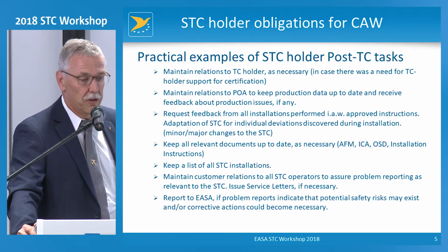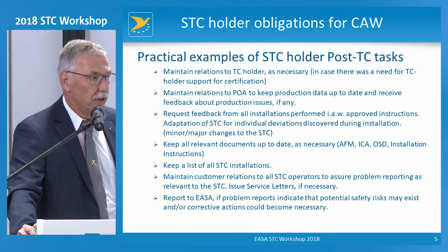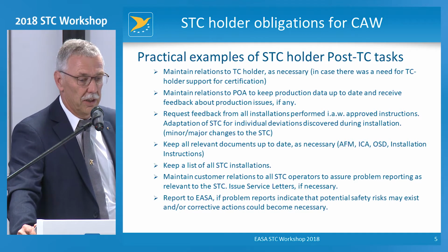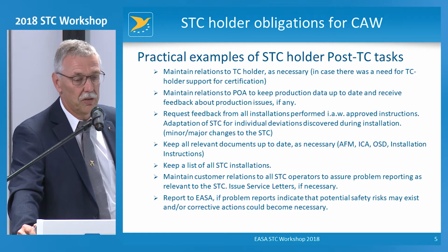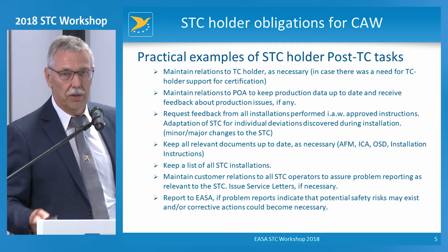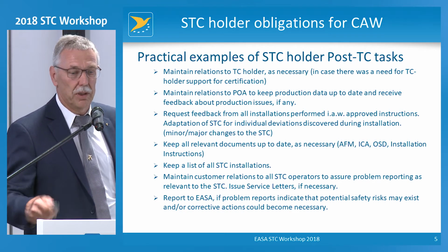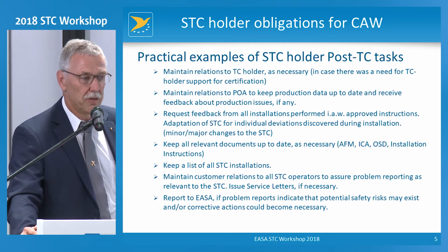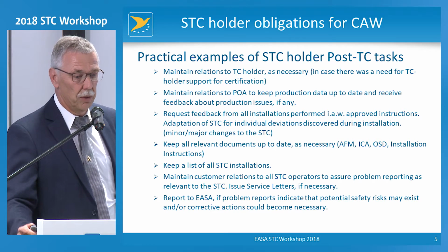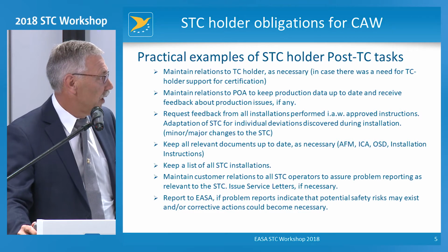You have to keep, obviously, all the relevant documents up to date and have a list of STC installations and maintain customer relations, so that in the case that STC customers have problems, you can inform everybody who has the same problem or could have the same problem what the solution can be. Certainly, the last line is the reporting to EASA.